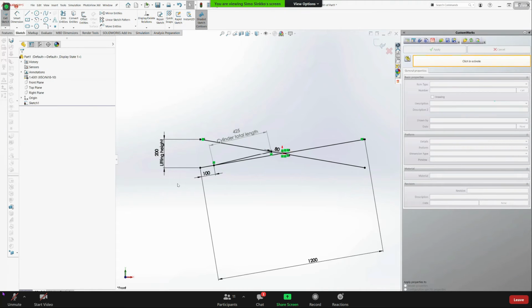And what do you think, what is the position of the scissor lift where you need the biggest force out of the cylinder? Is it the starting point or somewhere else? I'd say starting point, maybe, because in the starting point the legs are quite horizontal and therefore their Y component might be quite excessive.